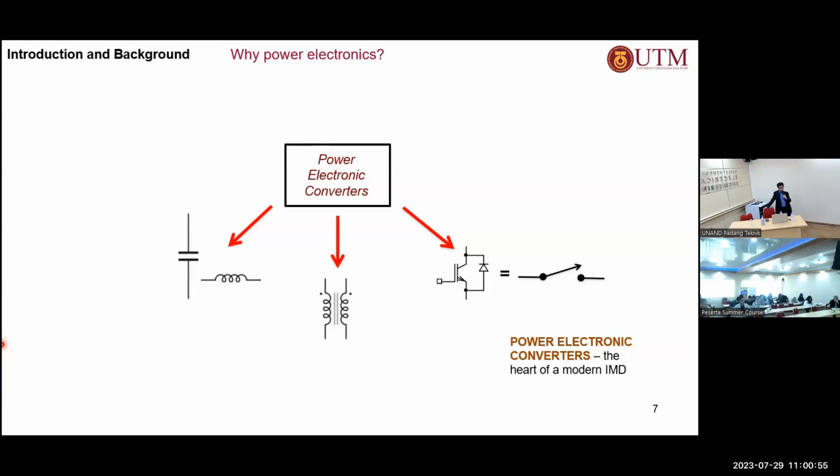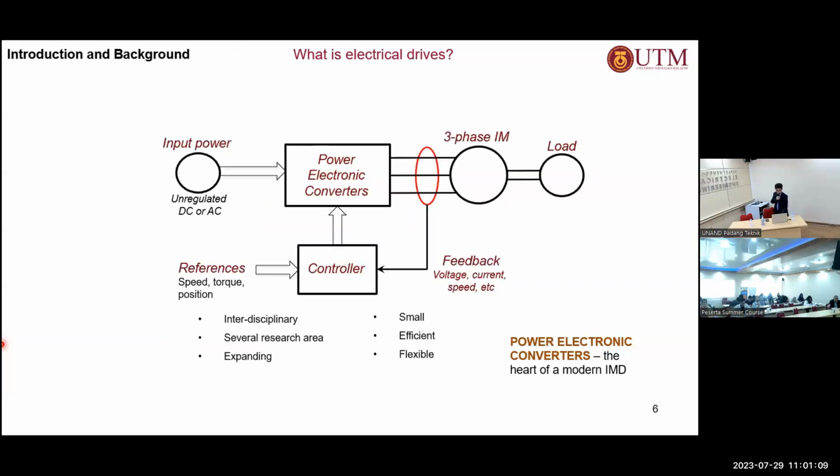resistance associated with the capacitor and inductance, as well as for the high frequency transformer. But ideally, the efficiency is going to be 100%, which means that whatever input you put into your power converters goes to the output, 100% efficiency. But even if you include these losses, which I said earlier, the efficiency is still going to be high. It can go as high as above 90%, okay? 90 or 95%.